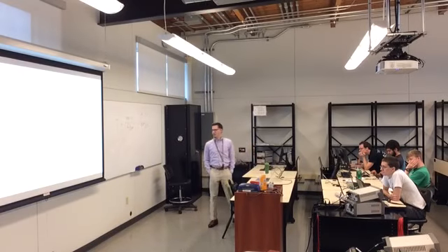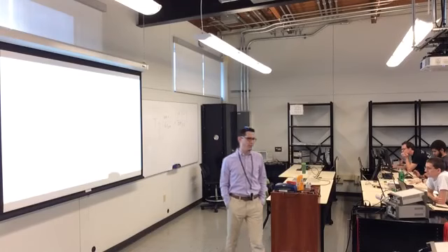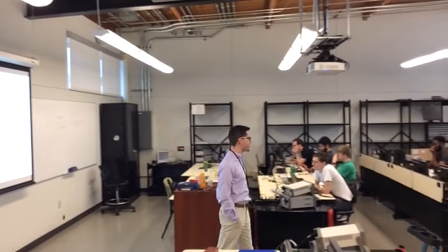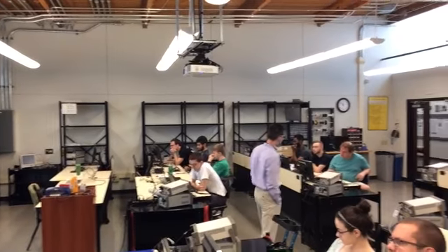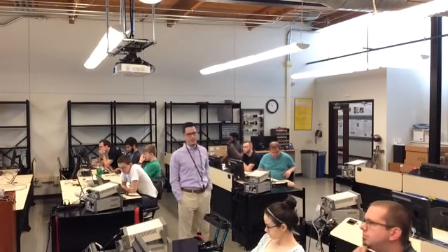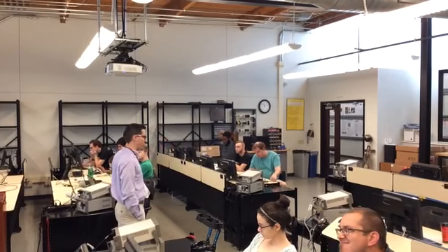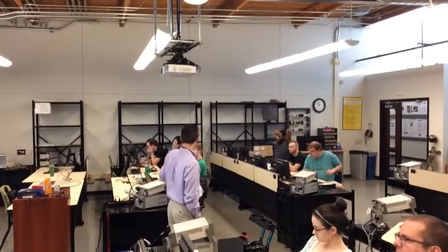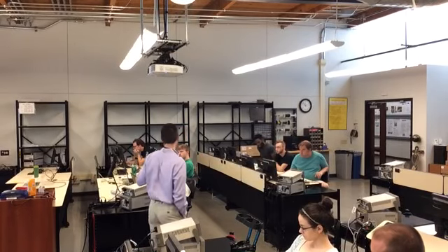When we get into timers, the reason you have a timer is because you want to know some amount of time has elapsed, and you don't want your processor to deal with it. That means we're going to start to get into interrupts. And honestly, interrupts are the main reason you have a microprocessor. You really just want to have your small program, start it up, and then have things be event-driven. You want them to be interrupt-driven.